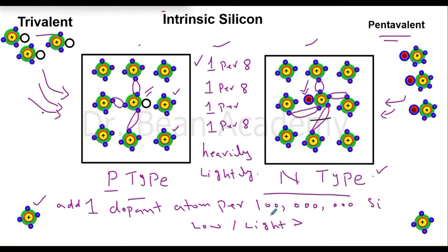You see, because I leave a large number of silicon atoms and then I replace one silicon atom with one dopant atom. Then I cross another 100 million silicon atoms. So this doping is really low. You can imagine from this number, because I didn't write it in scientific notation, that I am leaving a huge number of silicon atoms, and then I replace only one silicon atom after that with the dopant atom. So such type of doping is called low or light doping.